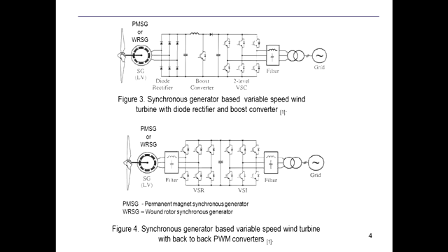All right. So we look at this circuit, which is called a boost converter. There is also, if you parallel switches here, the 6 switches, so this is like a diode rectifier plus 6 switches. So it looks like the same circuit as that, but this part acts as a rectifier, this part acts as an inverter. So we would be looking at how to control these and how to control these, all right? To extract the energy and so on.